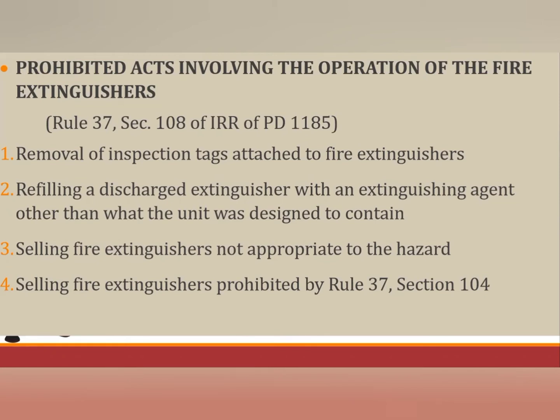Then refilling a discharged extinguisher with an extinguishing agent other than what the unit was designed to contain. Do not try or attempt to make use of other chemical contents other than what is designed for the fire extinguisher. Do not replace with another chemical content.